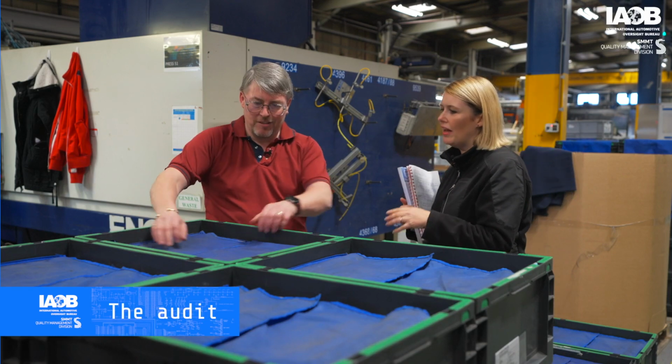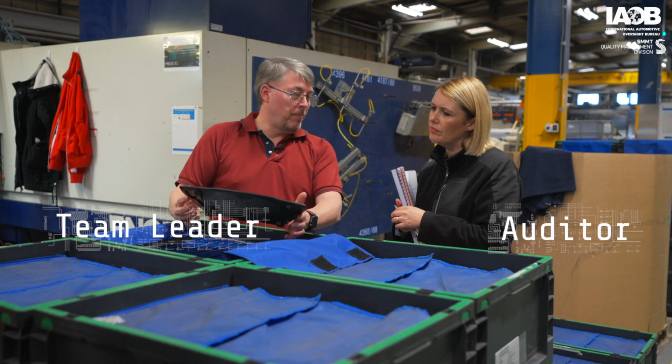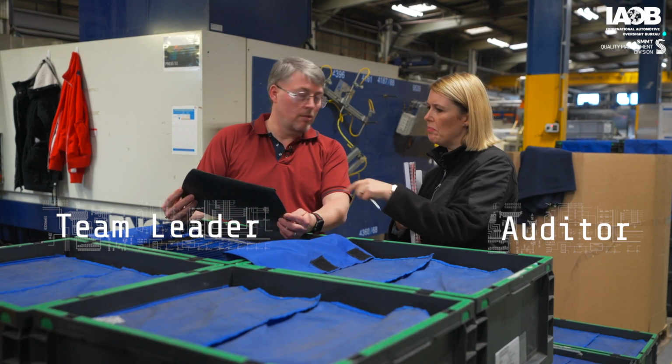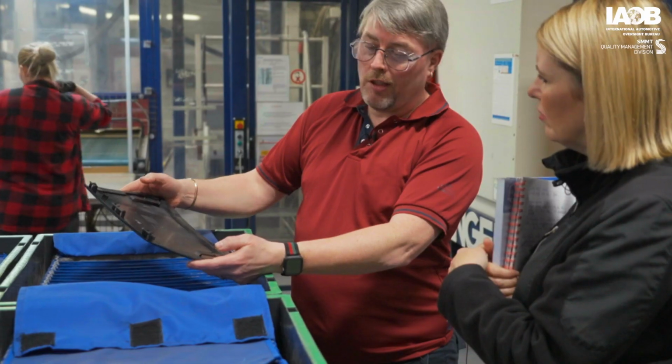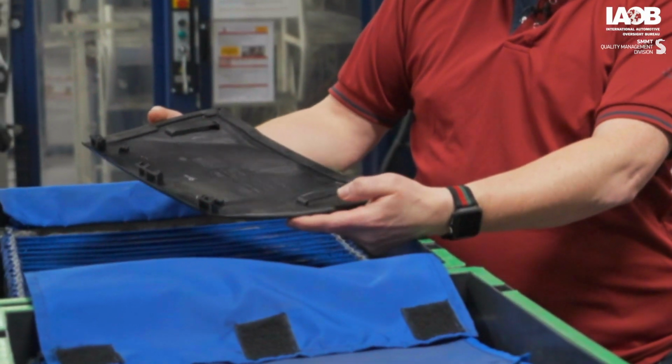Hi Brett. Hi, so could you tell me what you're doing here then? These are map pockets. They're moulded on the press behind. Okay. And what are the marks that I can see there? They're to say that the operator has checked that the parts are full and complete, and also to remind them to check for flash on the part.